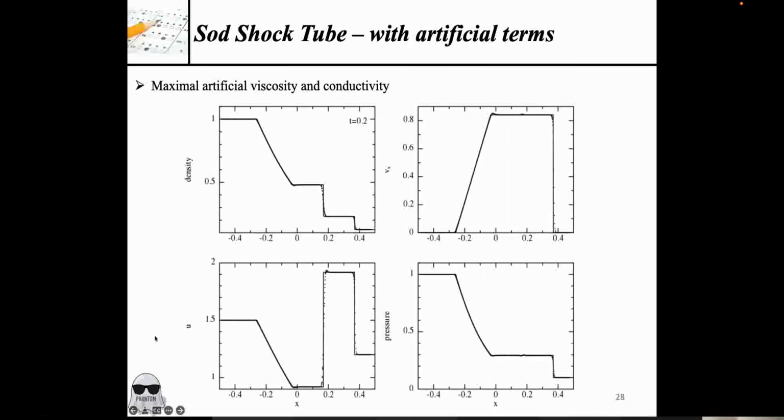And now we see that everything looks very good. All of our ringing is gone, our pressure blip is gone. We do have some smoothing issues right at the border, but given that by nature SPH typically smooths over shocks, this is not unexpected. If we were to run with higher resolutions, then we find that the shock front itself gets steeper and steeper, and we better match our resolution. So now that we put in these artificial terms, we basically have a very good working code, and we can very well reproduce this test case.